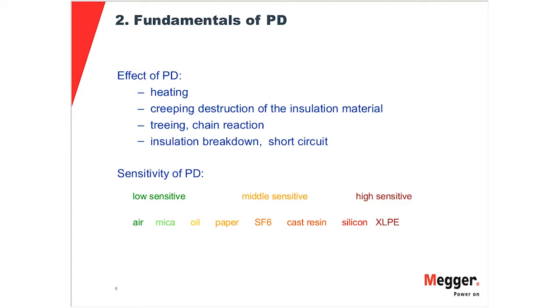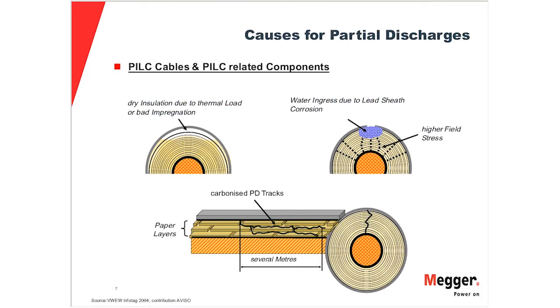That's basically what I try to express here with this page. Okay, now let's go a bit further. What can be the cause for partial discharge? You see here just a few examples. These are all related to either PILC cable, which are paper oil impregnated cable, or they are related accessories like